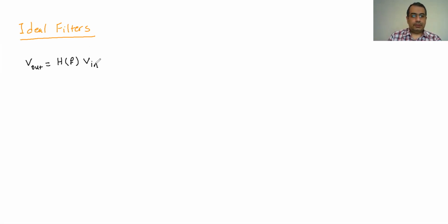So simply, if you have the signal in the frequency domain and want to filter, we just multiply it by the filter itself, or as I said, the transfer function of the filter. Simply, this is the filter in the frequency domain, and this is the input signal in the frequency domain. Just multiply them, and by multiplying them, we filter the input signal and get the output signal.